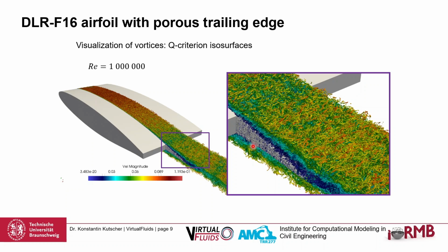So it was a so-called DNS simulation. That's y plus equal 1, if you want to know what I say. In normal language, it means that we resolve the so-called boundary layer, a full resolution of the aerodynamics on the surface of this wing.